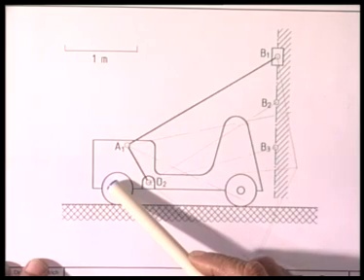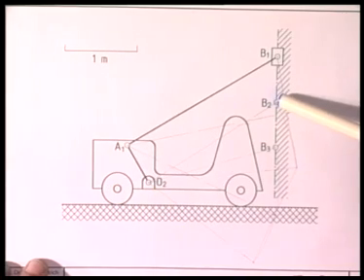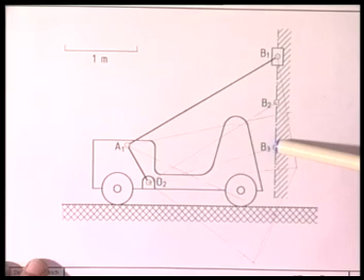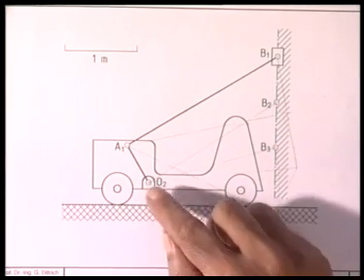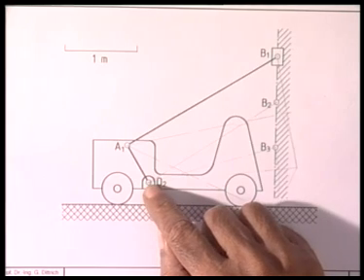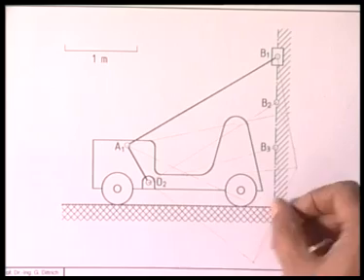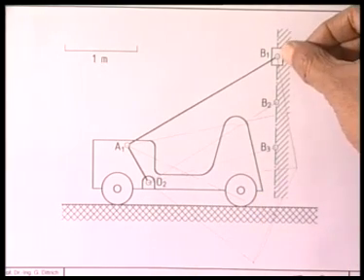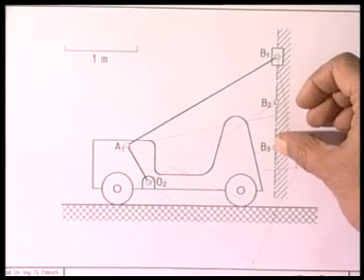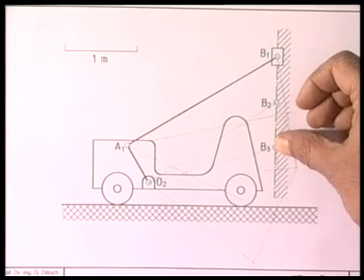Further 26 degree rotation of the crank will make the point B2 come up to B3. This we have already learned how to do. We choose O2 at a convenient location on the body of the truck. We have chosen this line conveniently at the front of the truck, and I have located B1, B2, B3 according to Chebyshev's spacing.